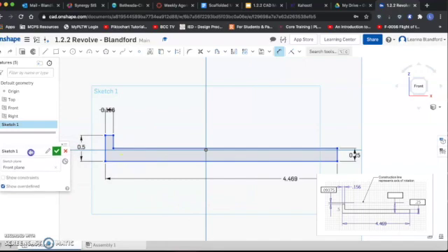So I have most of this shape done. Now you'll notice in the drawing above in this area there is a dashed line. That's called a construction line, and that's actually what allows us to revolve around to create that cylindrical shape. So what I'm going to do is I'm just going to grab my line tool, and I'm going to draw a horizontal line and hit the escape key. I'm then going to come up here to my construction button. I'm going to click on this line and then click on the construction button, and it's going to turn this into a dashed line.